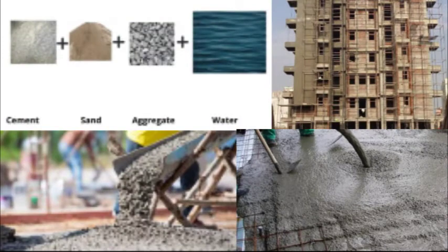We all know that concrete is a proportionate homogeneous mixture of cement as bonding material, fine aggregate that is sand, coarse aggregate that is stone chips in a range of sizes, and water in a cement mixer, and pouring the liquid into the framework till exactly the right level required. The concrete will become hard in a matter of hours, but takes a month to reach its full strength. Therefore, it is usually propped up until that period. During this time, the concrete must be cured or supplied with water on its surface, which it needs for the chemical reactions within to proceed properly.